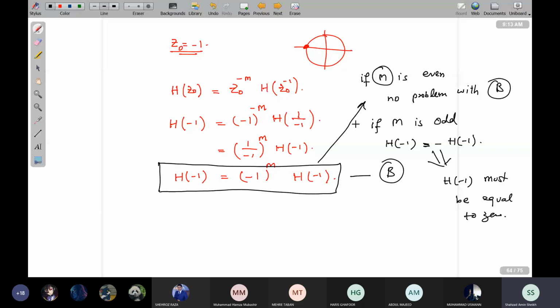So what is m? M is associated with number of taps. When m is even, number of taps are m plus 1. So when it is even, we are talking about odd number of taps, and n even is being discussed. So we are discussing type 1 and type 2. This means in type 2 filters, h of -1 must be equal to 0.